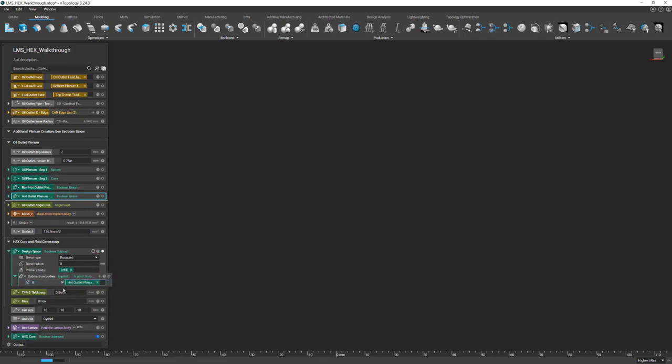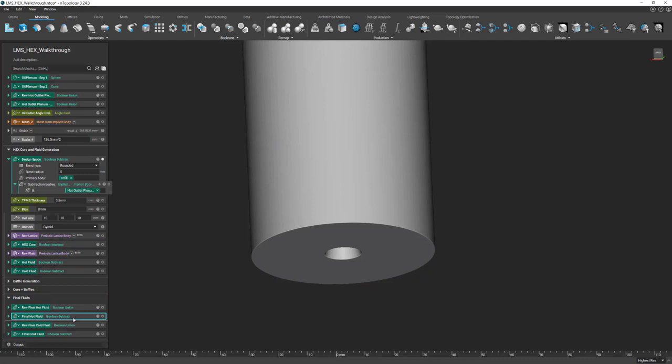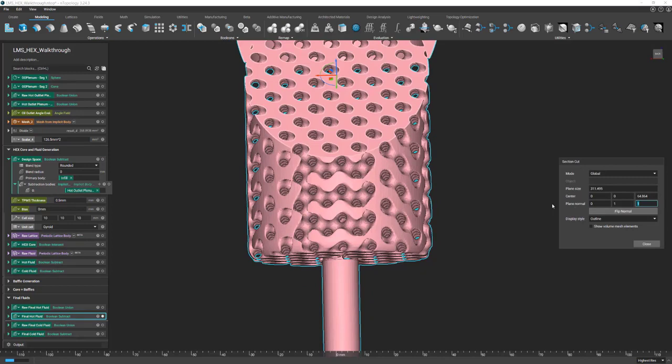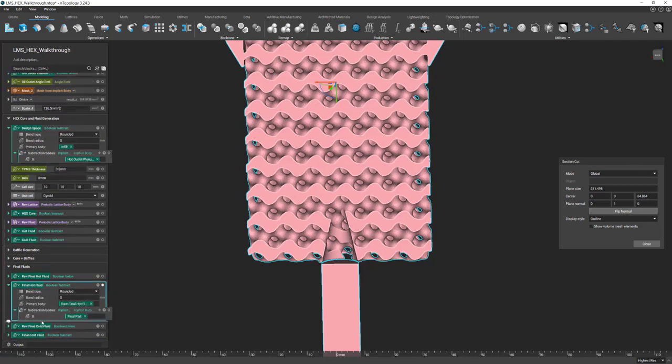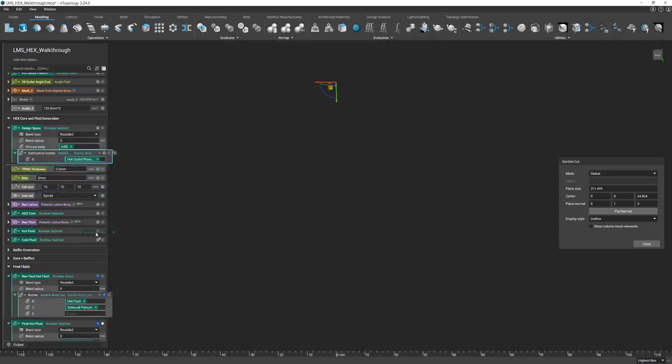Now the entire workflow that we just created is going to rerun. So if we come to our final outlet fluid and visualize this hot section and look at the cross section of it, we've now removed that body, but we don't have that fluid attached. So what we would do is come to our final hot fluid, and rather than this oil outlet fluid, we're going to capture the hot outlet plenum that we used to subtract from that design space. We'll pull this into here.